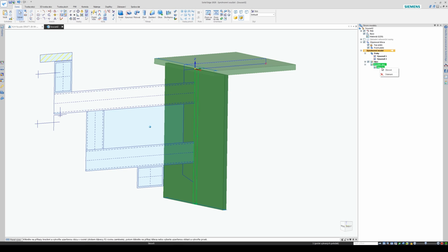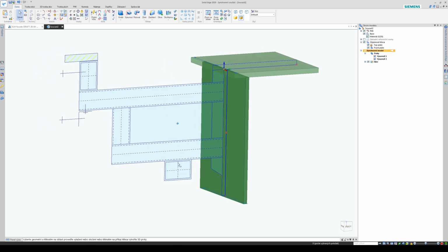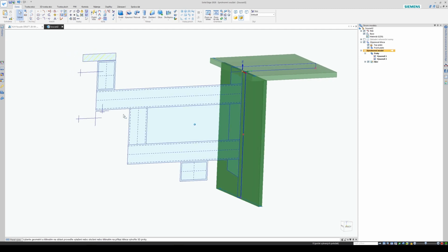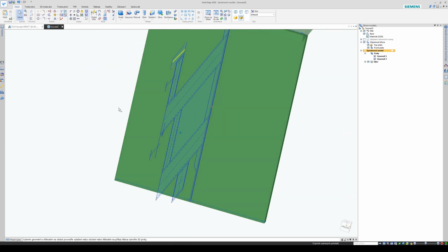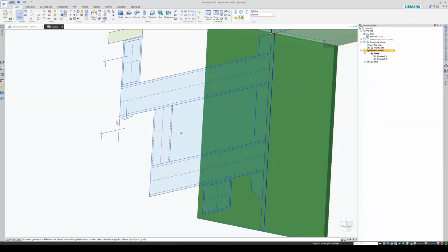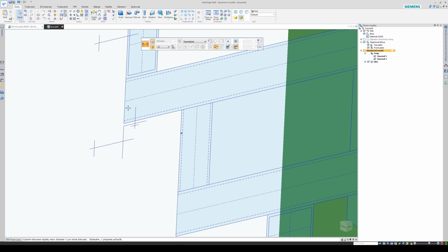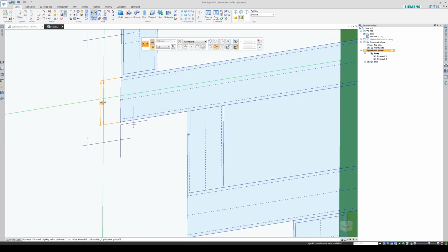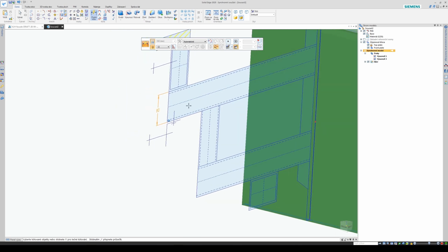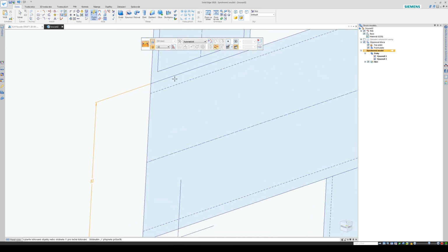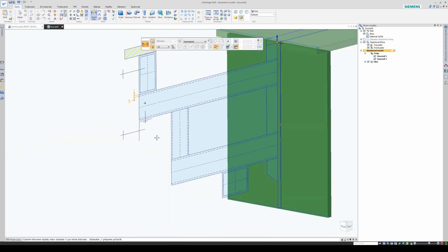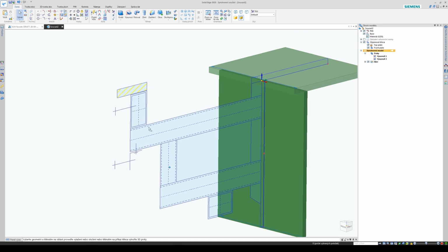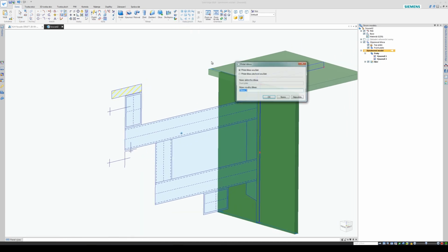Okay, let's again reuse sketches, and now we will construct these profiles. I think this is a rectangular hollow section. It's 80 millimeters. I think it will be square, 80 by 80, and the wall thickness is 5 millimeters. Okay, so let's quickly construct it.